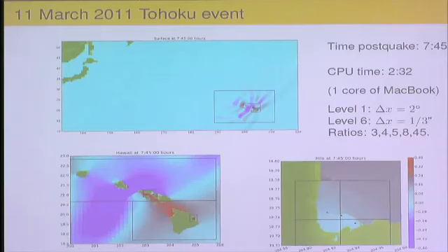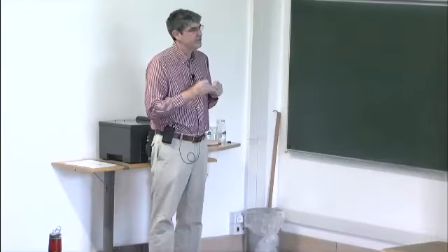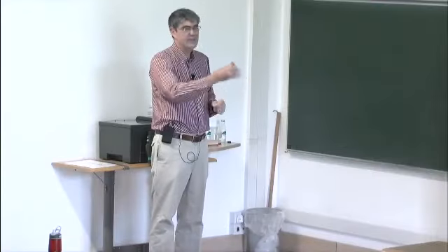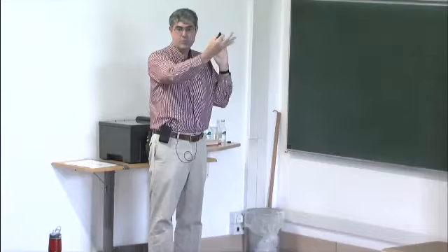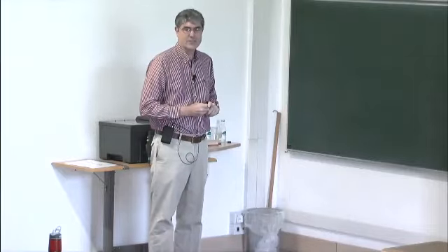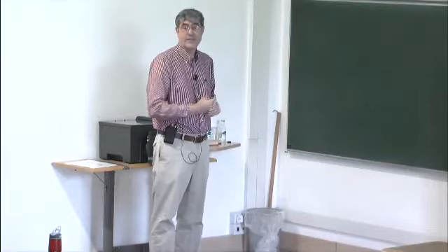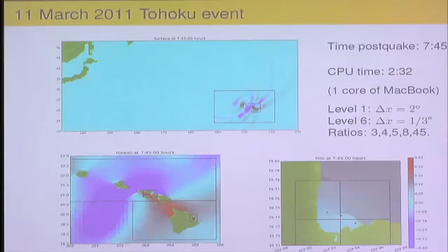Also, at the outflow boundary here where the waves are leaving the domain, what we do is simply extrapolation from the grid cells adjacent to the boundary into the ghost cells. And then when you solve the Riemann problem between a cell and the adjacent ghost cell, if they have the same value in them, then there's no waves, or there's 0 strength waves in that Riemann solution. And in particular, there's no incoming waves. And that's not a perfect non-reflecting boundary condition, but it does quite well. And we found that it's quite adequate for many problems.